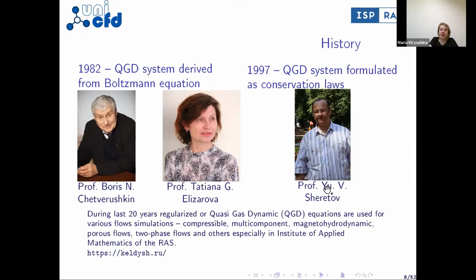The principal and essential distinction of the QGD approach from the Navier-Stokes theory is the use of the spatial time averaging procedure for the definition of the main gas dynamic quantities: density, velocity, and temperature. The additional smoothing with respect to time is the cause of appearance of additional dissipative summands in the equations, by which the QGD systems formally differ from the Navier-Stokes system.